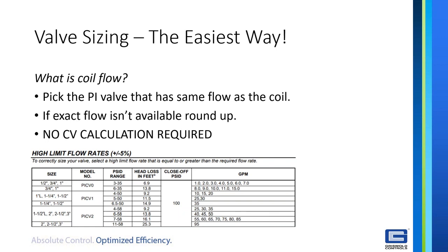And there are some contractors that have done this, and then they use that table and they set the valve in the field by basically limiting the actuator so that it doesn't go past the flow rate where they want it to be. So you could make the overall job easier by doing it that way, but then you are still having to set it up in the field with the contractor. But valve sizing wise, this is definitely the easiest way and the easiest to size.